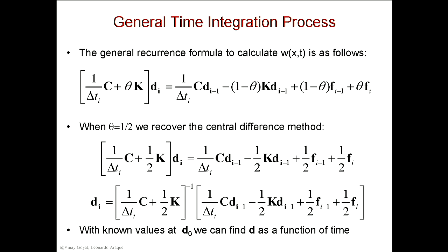The only difference between what we're doing there and today is that now things are a function of time. That's the only difference. So we're not discretizing time using finite elements. That will not work very well. Finite difference is a much more appropriate technique for this methodology, and that's how commercial codes such as Abaqus and Nastran are coded up.